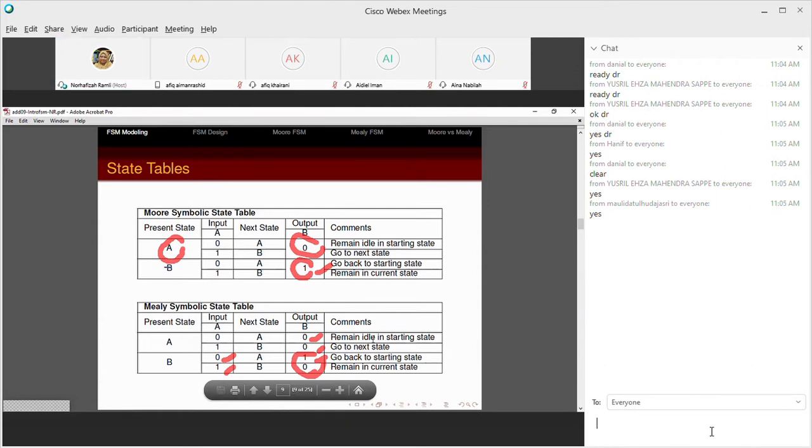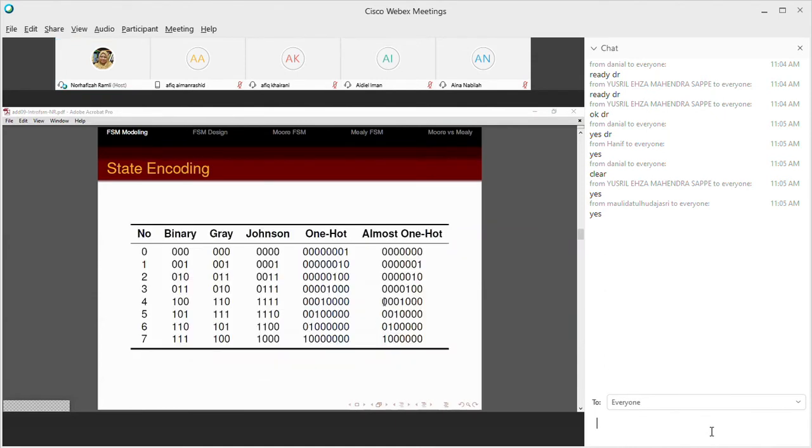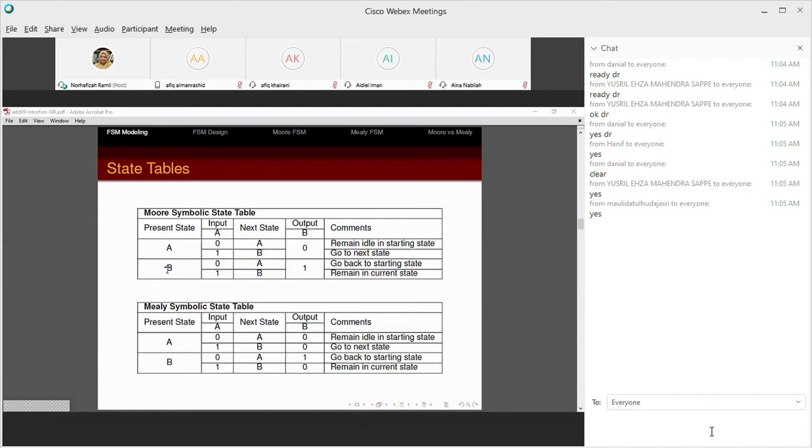Now, right. In the previous one, you didn't give any names to your state. Just use variable A or S0, S1. Okay? But that symbol here is already in binary. So again, we are talking about digital systems. We are talking about binary systems. Therefore, each of the states has to be given a binary number or binary code that represents the name or the coding for the state.